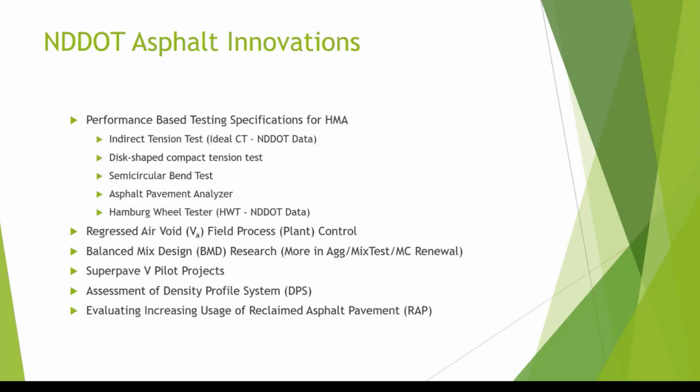The density profiling system is one advance that I think is going to greatly impact and has greatly impacted the paving process and also the acceptance process. And ultimately, I think will be the acceptance tool as opposed to going out and running a core every 1,000 feet. So it keeps you off the road at 5:30 in the morning in the middle of live traffic trying to take cores and then patch those core holes. So we'll talk about that and then RAP as well.